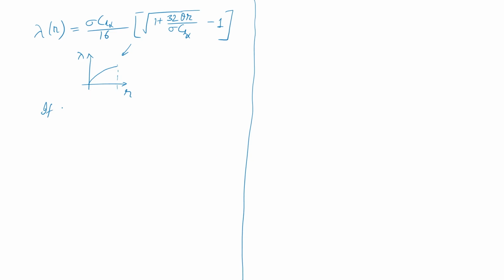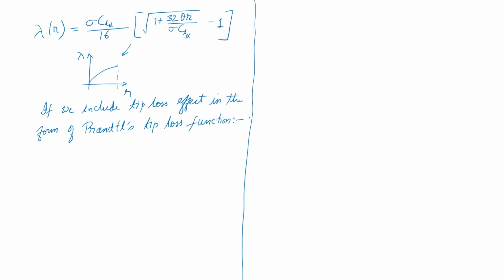So, if we include the tip loss effect, in the form of tip loss factor, or rather we call it Prandtl's tip loss function, we are going to introduce a new function called Prandtl tip loss function given by capital F, and modify this expression for my inflow like this,